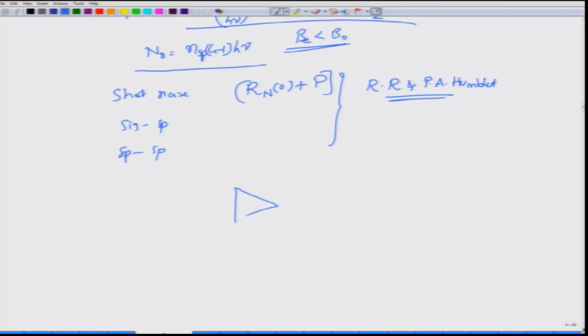To evaluate that, let us look at this situation, okay. We have some optical input to this, okay, and then there is an amplifier with a gain G. This optical input, if you give it to a photodetector, will produce a certain photocurrent, and therefore there will be a certain signal to noise ratio here. If you assume an ideal photodetector, it will introduce only a little bit of noise, but that noise can be characterized by looking at the input signal to noise ratio.